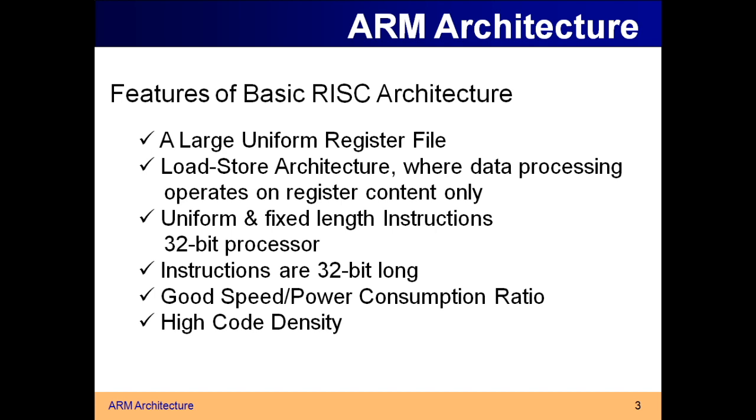Say for example, there is an instruction known as ADD EQ, that is one instruction. ADD EQ means you will be performing addition of two registers and the result will be stored to another register. This operation will be done only if the zero flag is set. That is meant by EQ. EQ means equal to. See, when the zero flag is set, then only the operation will be done.